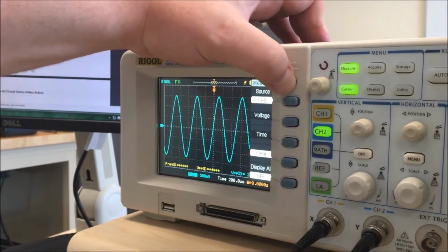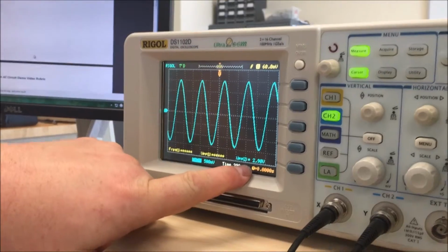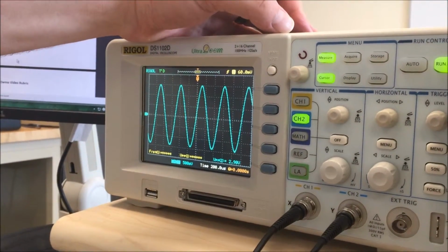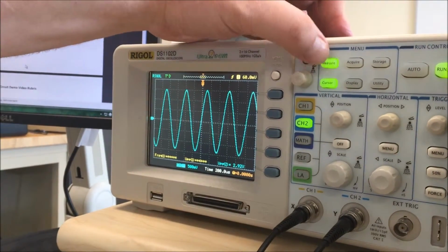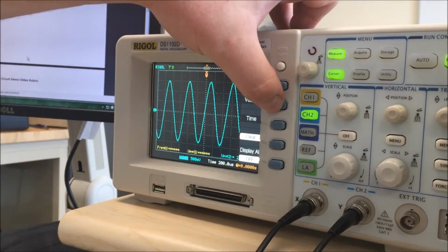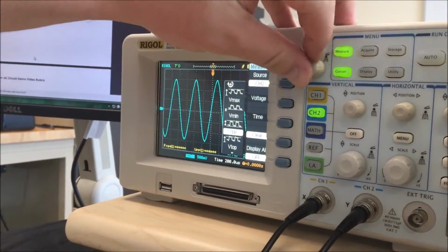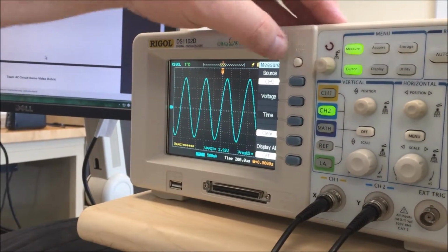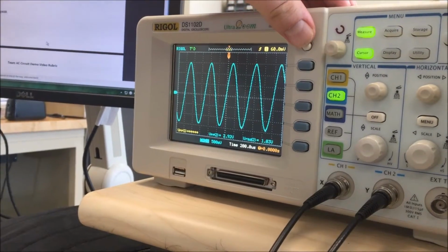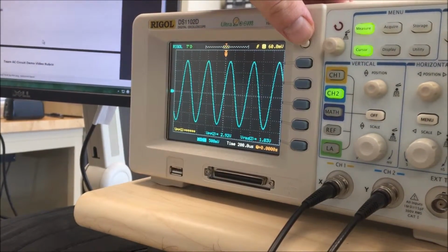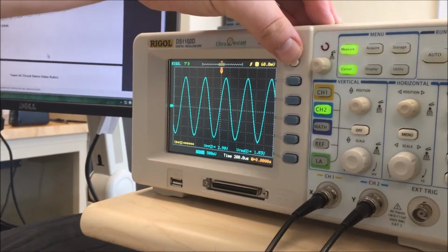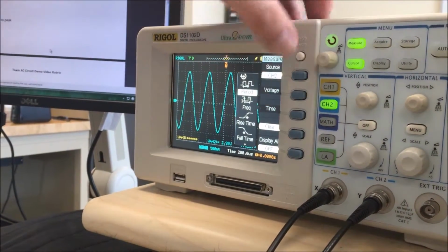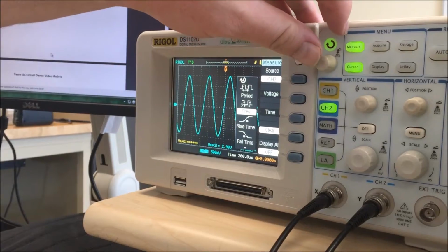To see the peak-to-peak measurement, it's right down here, 2.9, fluctuating a little bit, but it's around that point. To move on to the RMS, we'll go back into the measurement sources, go down a little bit to the RMS, remove the menu, and it's 1.03 volts. Moving on to the frequency, we'll come back here, do the time, and I'm sorry, the period.